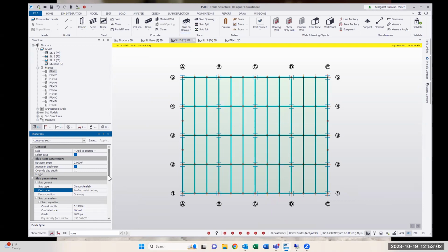What does decomposition mean? Decomposition is basically which way you direct your loadings on a slab. So with slab area load, you kind of manipulate the load. Like, oh, it's going to go over to this beam, and that's the load on that beam. You follow the load paths. Decomposition is basically using the load paths to determine the loading on other members. Where does that load go to is the decomposition.